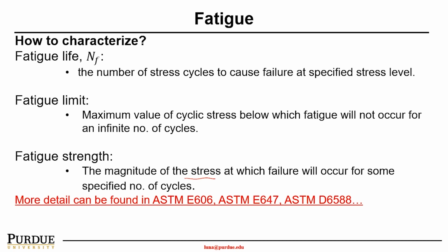So more detailed testing can be found in ASTM E606, ASTM E647, or ASTM D6588. It depends on what material you are testing, right, and your loading speed. This type of testing standard typically gives you very specific information on how to fabricate your testing coupons, how many cyclic load cycles you're going to go through, and your loading speed and such.